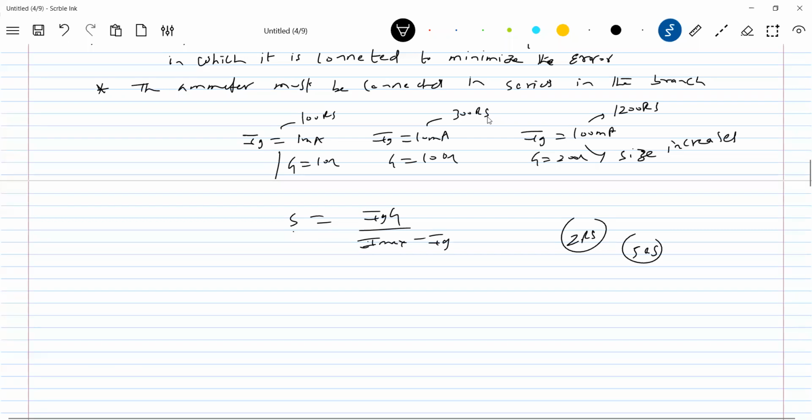So with the construction of a galvanometer for very high galvanometer current, what happens? The cost and size will increase, and also the maintenance problem. The error will be more. That's why usually we don't get even 100 milliampere. Usually 10 is the upper limit, is what I have seen. 100 milliampere is used in some applications, but a lot of problems will be there. So in the lab, usually you come across 10, 1 milliampere or even microampere.